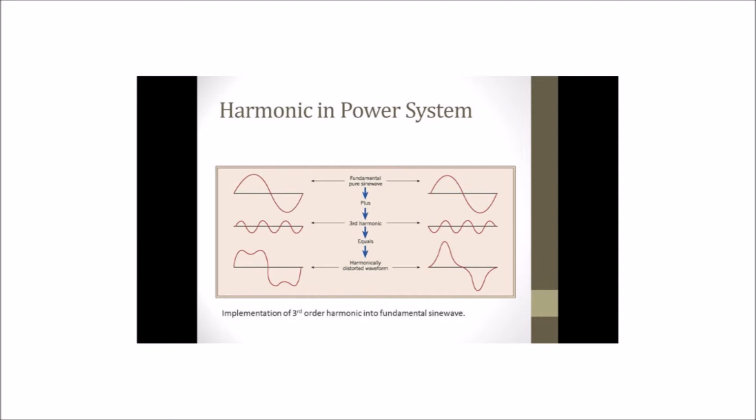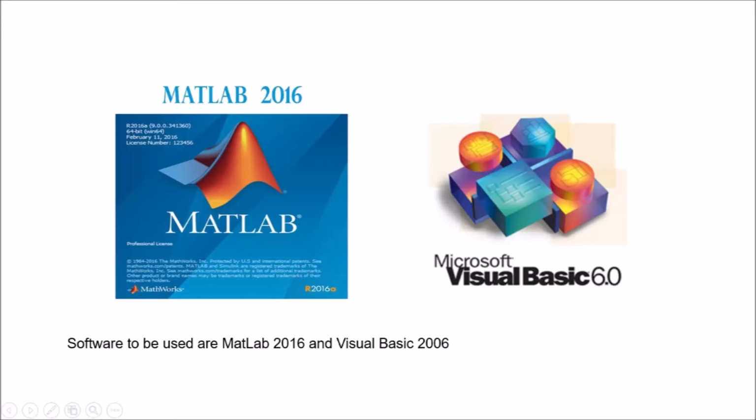Harmonics flow into the electrical system because of nonlinear electronic switching devices such as variable frequency drives, computer power supplies, and energy efficient lighting. One of the major effects of power system harmonics is to increase the current in the system. This is particularly the case for the third harmonic, which causes a sharp increase in the zero sequence current and therefore increases the current in the neutral conductor.